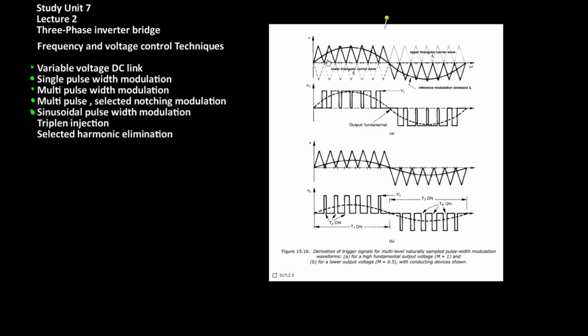The problem is that if the design is not that good, then there will be an asynchronous behavior which starts to creep in as the reference signal and the sawtooth start to drift away from each other. And what this means is that the system will start to behave like an asynchronous one. Essentially what the asynchronous behavior does is that the sinusoid will not resolve completely within one cycle. So what happens is that this pulse train starts to drift with frequency, and this will present as a very low frequency drift in voltage at the output.